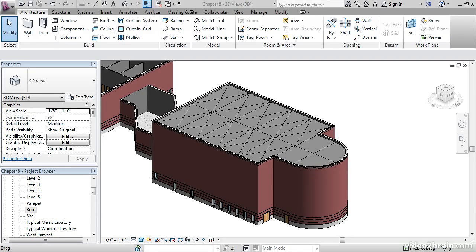In this lesson, we're going to pitch our roof in multiple locations to roof drains. The problem with flat roofs is, if they were truly flat, we'd be carrying quite a bit of water weight. When we design a roof, the only concern is where the water is going and how we're getting it there. That's where the art of tapering insulation comes into play. Right now we have a roof set up to do just that, to taper.